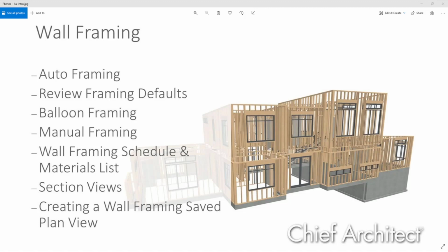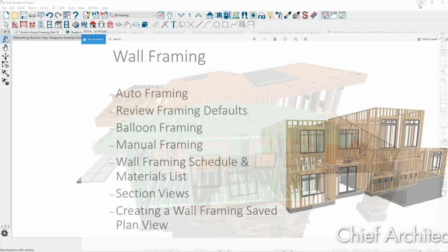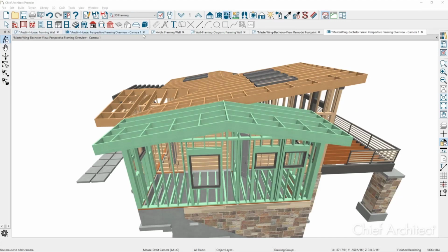Well, thanks for calling in, Jason. How would you frame the door in the concrete wall? Is there wood involved? Is it just cutting out the concrete itself? Yeah, so what they do is, because they don't know what's in the concrete, the engineer will specify the king stud, jack stud, header type scenario. Sure. The opening might be, call it 4 inches wider on either side. Right. So I've been doing that by hand, but I was trying to think if there's a better way.